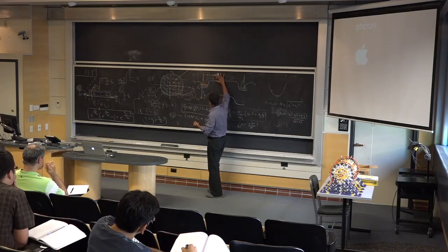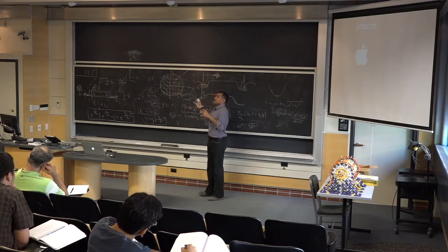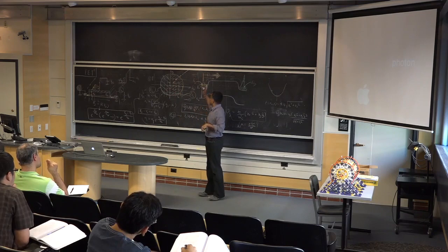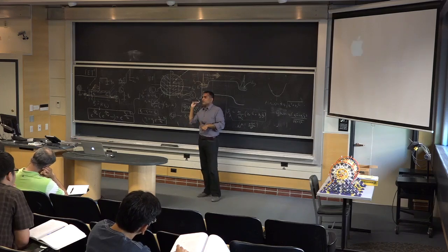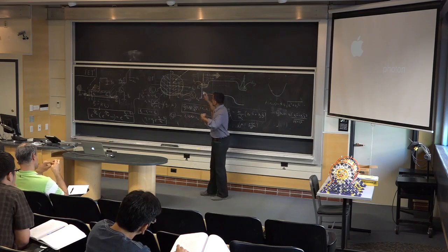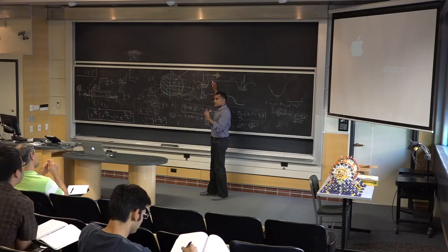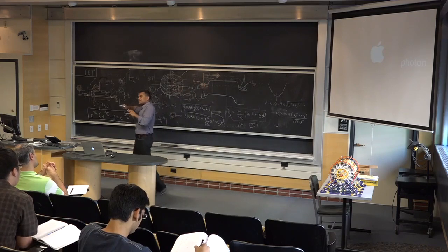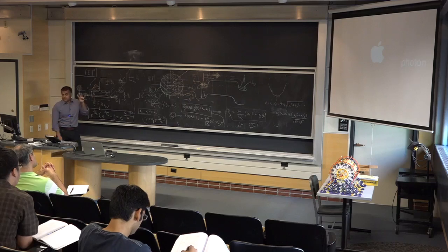the Fermi level of the right-going carriers becomes this. After all the reflections, all that has happened, it becomes this. So that's really what I'm doing. So we're saying, let's look at the steady state, right? Once you have turned on the voltage and everything, but what you said is exactly correct. There is reflection, and there is refraction, Snell's law, all that stuff goes on here too. And if the effective masses are different, then you have quite a bit of reflections. If the effective masses are similar, then it looks more like the same medium but going at an angle. Almost, not exactly the same, but it's very similar in many aspects of it.